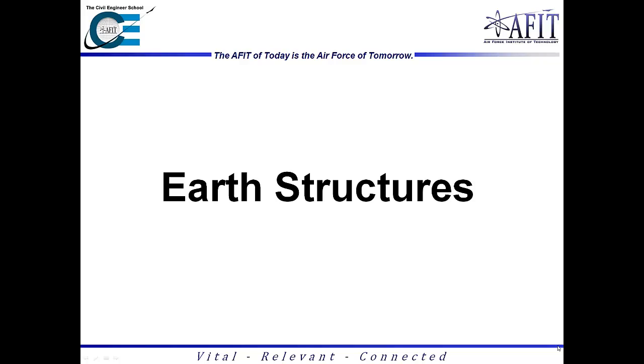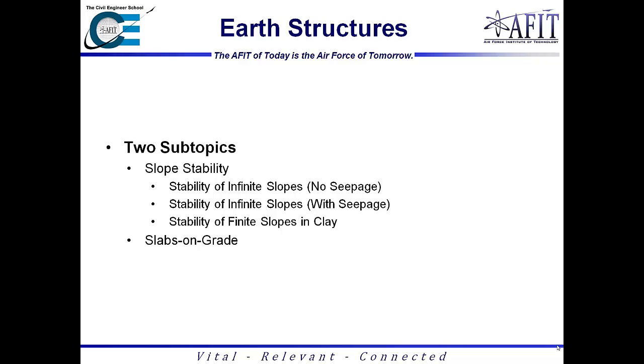The next topic we're going to get into is earth structures. This section has two subtopics: slope stability, which covers the stability of infinite slopes with and without seepage, and the stability of finite slopes in clay. The last subtopic will be slabs on grade. Since we don't really anticipate you having to design a slab on grade, this will be more of an introduction to them and talk about some rules of thumb for it.